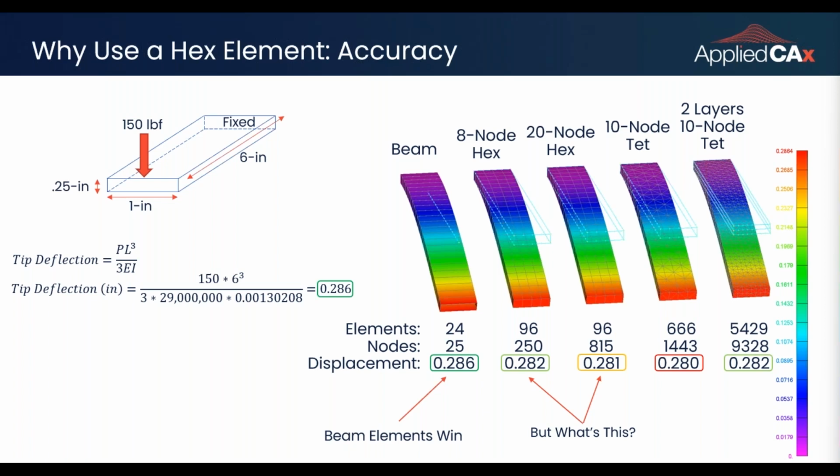I didn't bother including the linear 4-node version of the tet element. The Nastran user's manual states very clearly that you should always use the 10-node tets for all structural simulations whenever you're solving for displacement and stress. The 4-node tet is overly stiff for these applications. In general, you should minimize your use of the 4-node tet element, especially in areas of high stress.